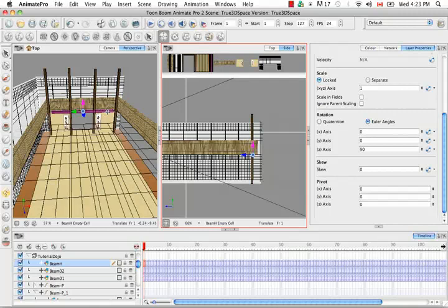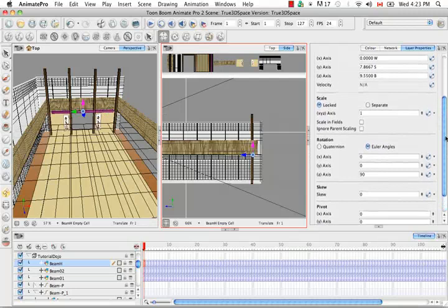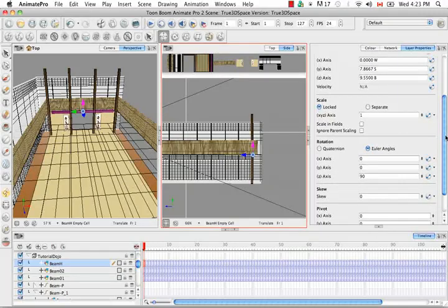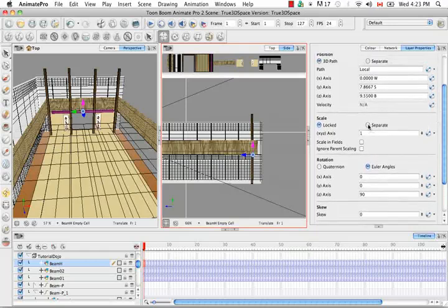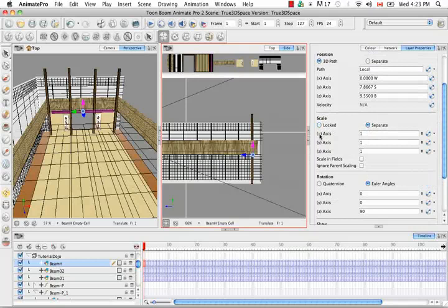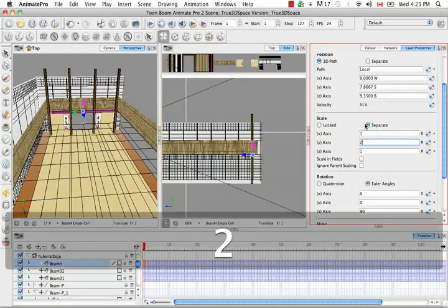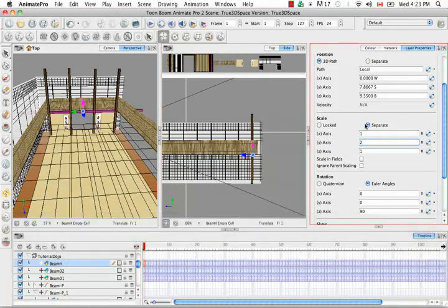So actually, let's do a test here. If I scale the symbol, I'm not sure all of them will scale systematically. However, if I scale the drawing inside the symbol, it might make a difference. So let's scale separate. I want to make it longer, so that's the y-axis. Let's do something extreme like doubling it. So doubled it. Oh, but these ones down here did not double because we would have seen the length drop or increase from the top. So in fact, it's really just the drawing that makes a difference, and I'll show you what I mean.